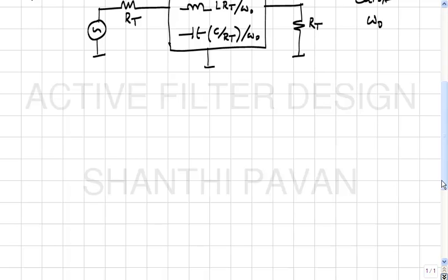The only new player I have with me is the transistor, which when biased in the active region can be made to behave like a voltage controlled current source. In other words, using transistors we can in principle make all the four control sources. We can make the voltage control voltage source, the voltage control current source, current control voltage source, and the current control current source.